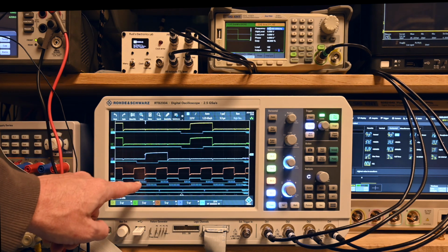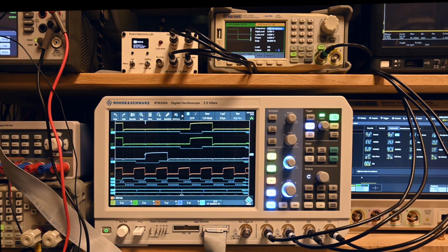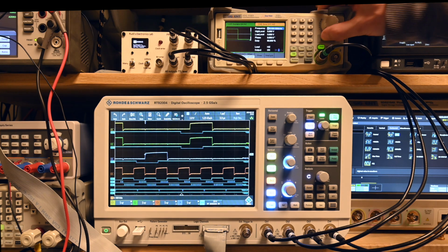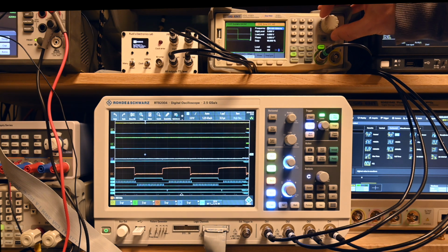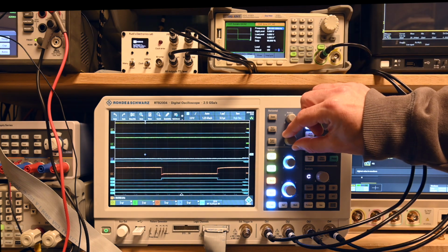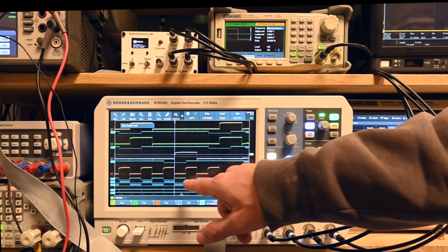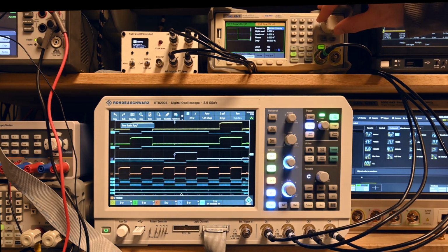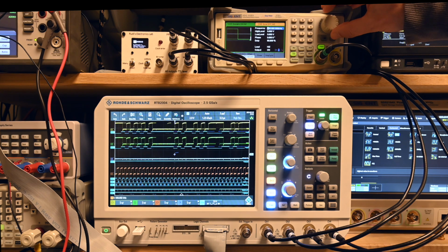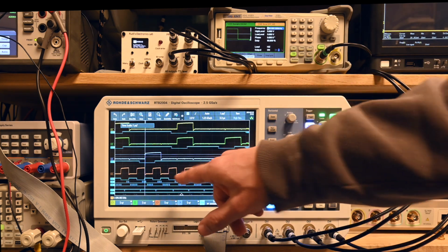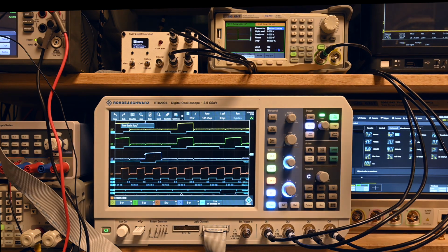So basically what we see here is the wait state of the device. And if we go to a lower clock frequency, then we would see that we have many more wait states. While if we go to a higher clock frequency, we will of course see that every time we have fewer wait states, and then it already has to deliver the next value.